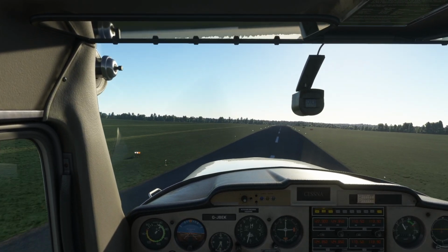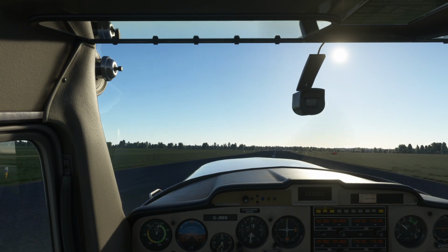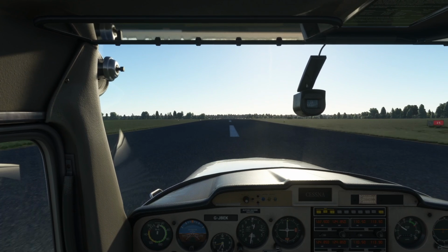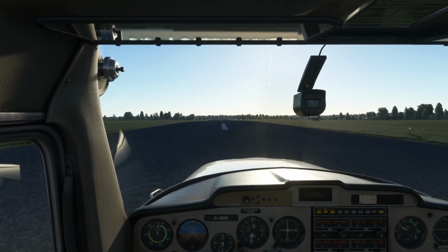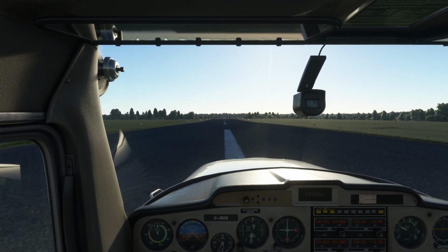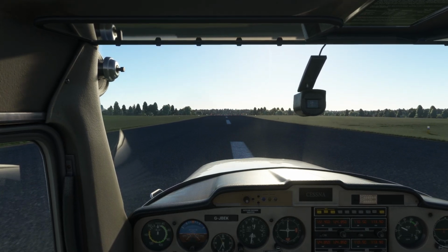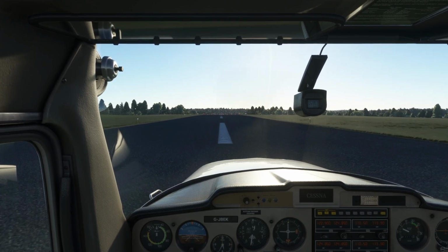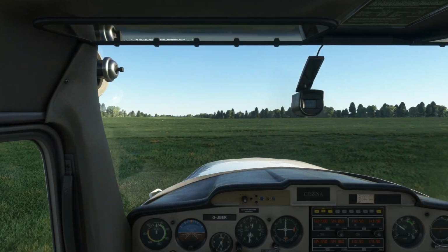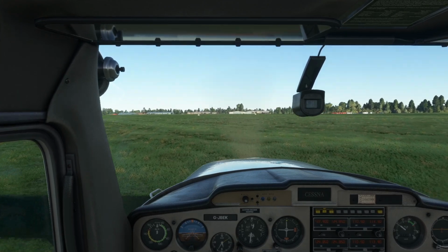So cut the throttle, manage the crab angle, and then just before you're about to fall onto the runway, you straighten the plane up on the rudder and maintain the pressure, which keeps you in a straight line without weaving all over the place. So yeah, there were some mistakes in there, you know, some more things to practice, but that's the whole point of this. This is really to follow real world practices in the simulator and to learn myself, and you know, to show other people that these exercises really are worth it. It will improve your flying. It's certainly improving mine.